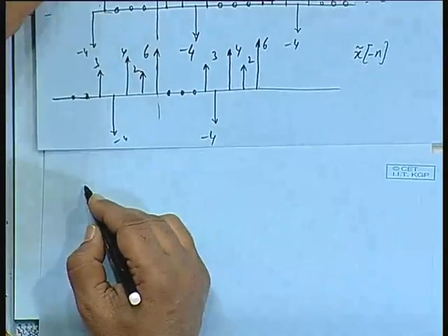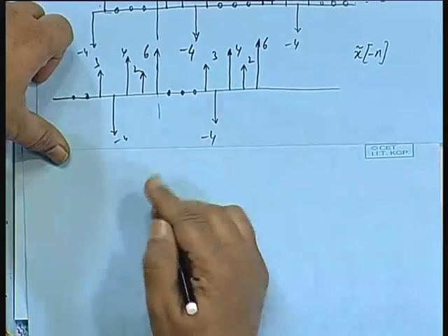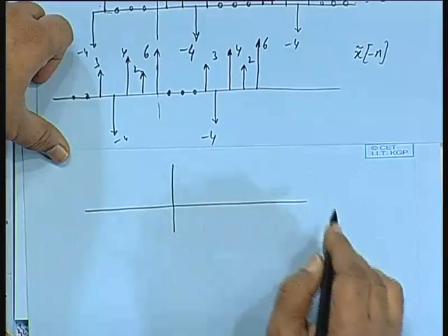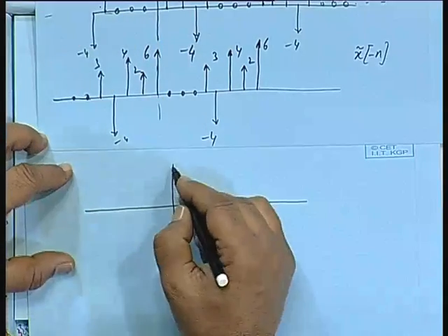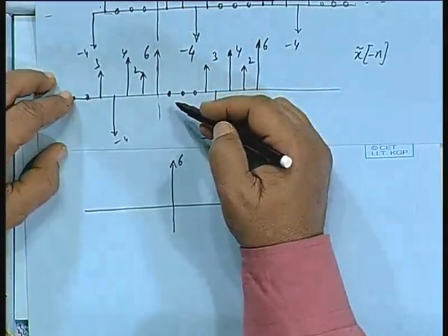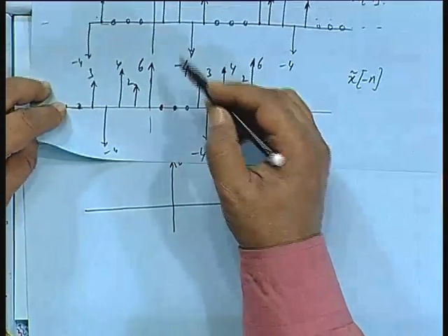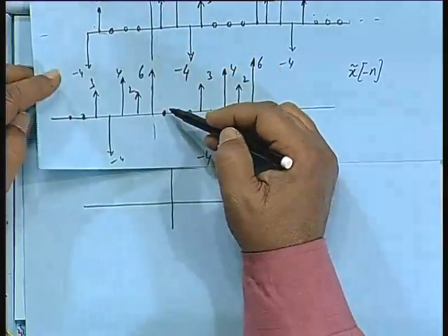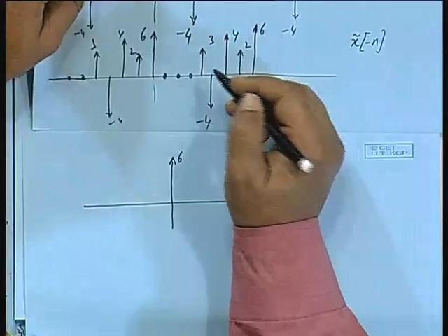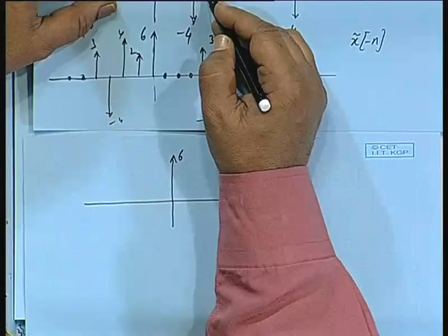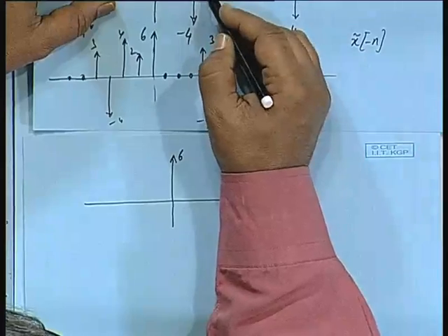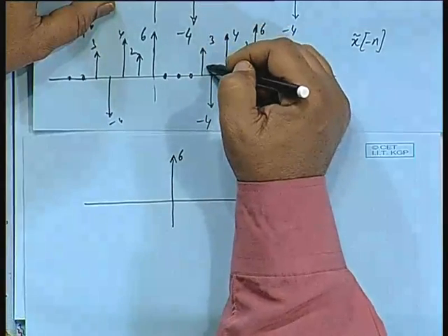So, take the average and then tell me what x_e[n] will be like. If you permit me to draw x_e[n], 6 plus 6 by 2, so that will be 6. Here you see the advantage of padding zeros: 2 plus 0 by 2, so all these values will be halved, except at the 5th point, whose index is N/2, that will be again 3 plus 3.